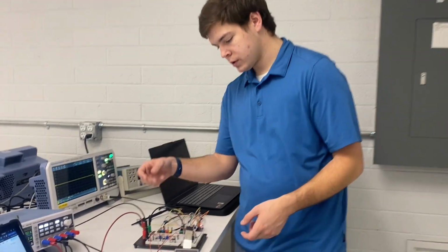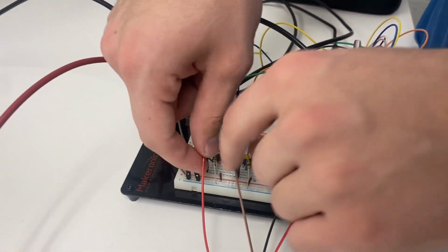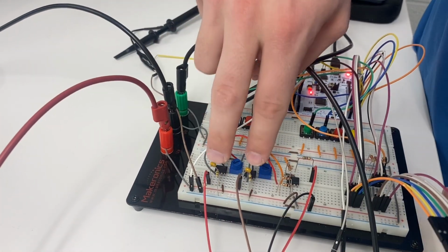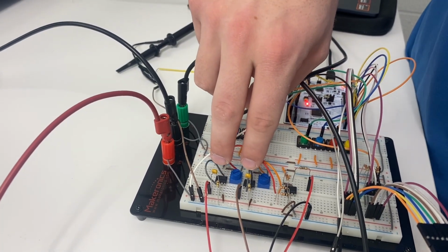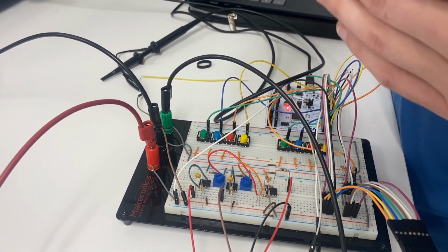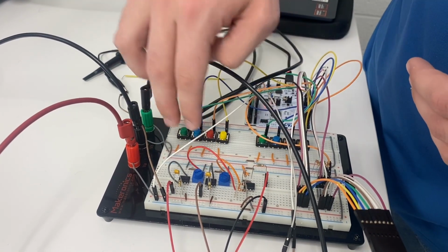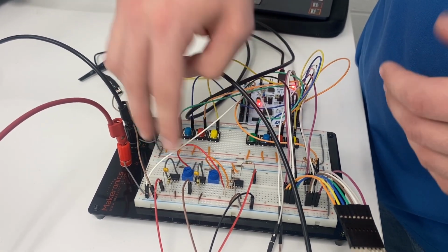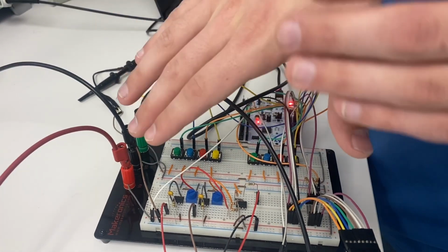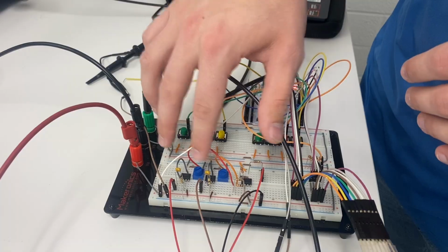Once we have those values that are output from the lookup tables, we send those to our digital to analog converters. And we're using both channels of the DAC. One of them is used for our manual output, the notes we actually play, and the other is used for the notes we've recorded and are playing back. Once those values come from the digital to analog converters from the microcontroller, they're sent through a simple RC high pass filter to remove the DC offset so that we don't blow our speaker with it. That is then run into an op amp serving as a buffer so that the rest of the circuit doesn't load that filter and change the cutoff frequency.